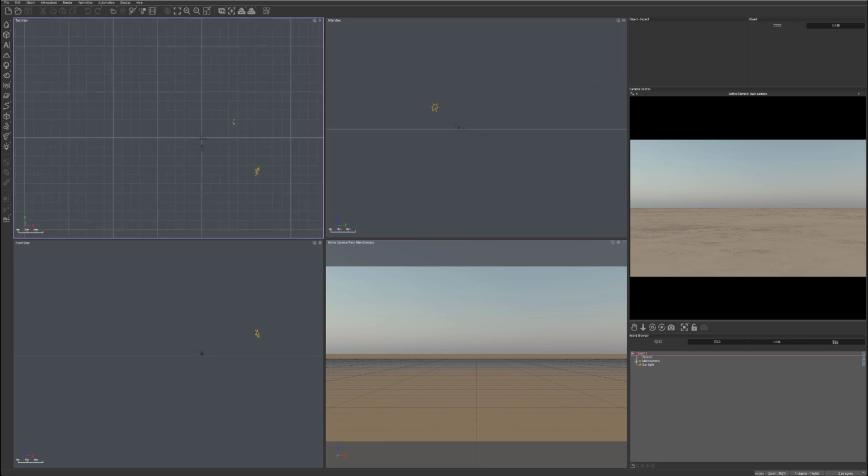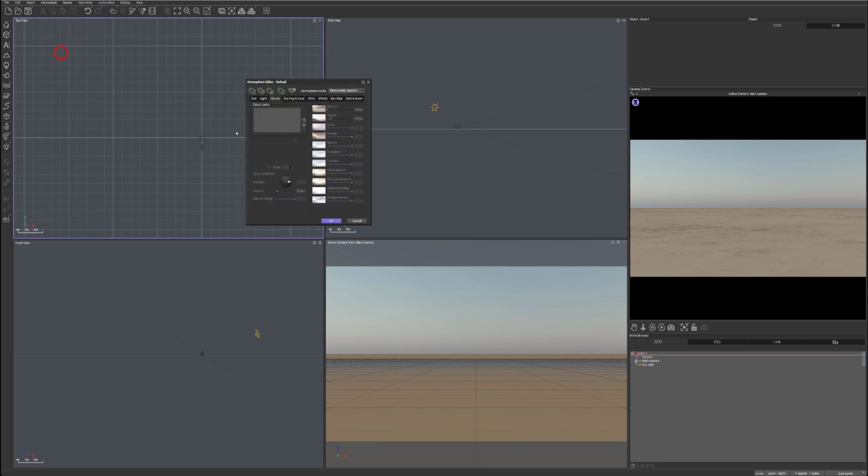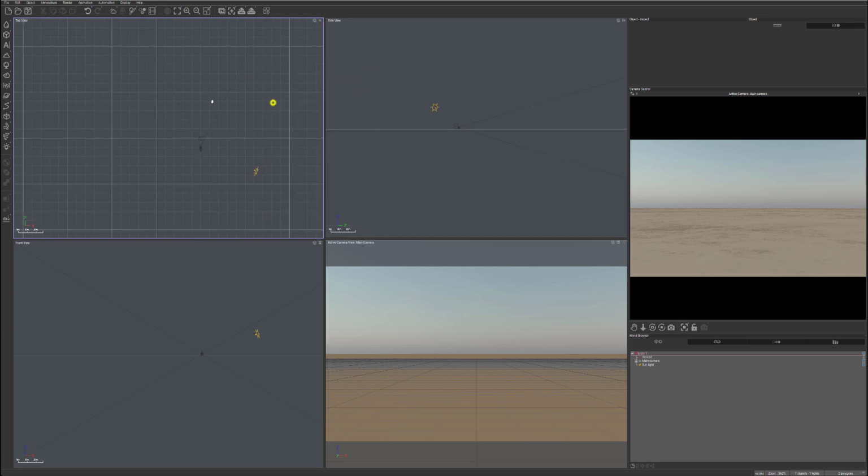Usually I use this workflow to optimize how my system works, because I know the atmosphere settings. If we edit atmosphere right now, it will be more resource costing on our system as a render, because we're going with volumetric clouds and other stuff. We'll start having some performance issues that will affect our preview. So what I found over the years working with Vue is my personal optimum. It may not necessarily work for you, but for me, this is how I work.